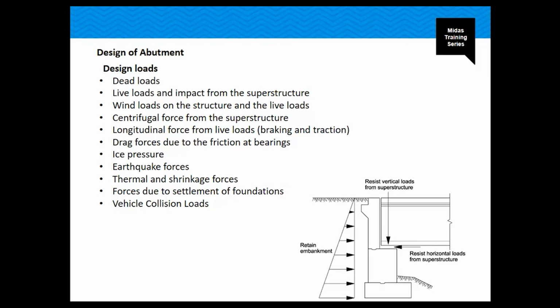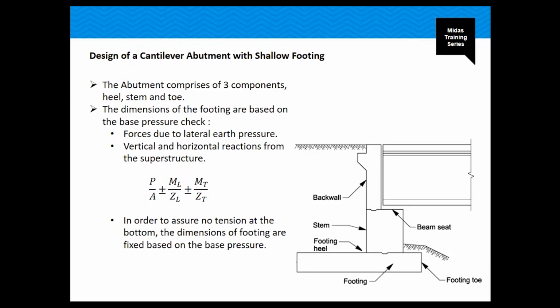Depending on the location of the project, there are also some other types of loads that need to be considered. For the abutments specifically, there are different loads that need to be considered as main loads, which are the soil pressure that acts on the pier, and also the earth pressure, the earthquake pressures that can act on the pier as well. There are some factors in each code that provide us with the calculation of the different loading.